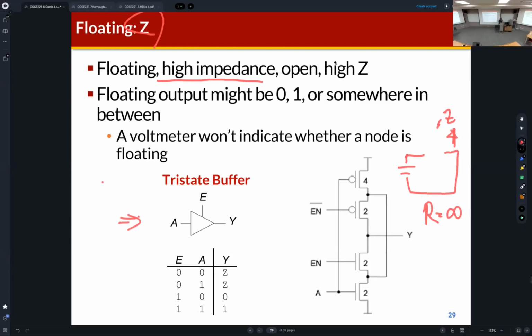Okay. So why tri-state? Tri means three, and state. I explained that a circuit has only two levels, 0 and 1. But this circuit has another output signal, high Z, high impedance. So the tri-state buffer has two inputs: this is input A, and this is the control input signal, called E, or enable.